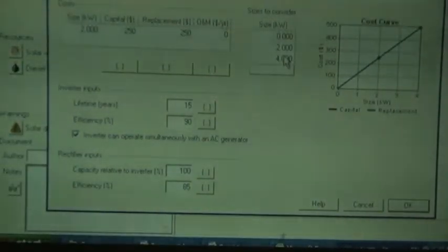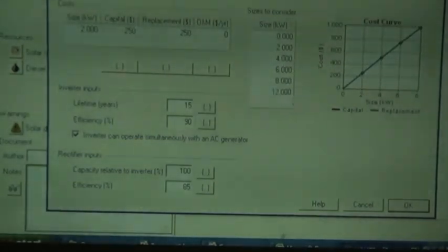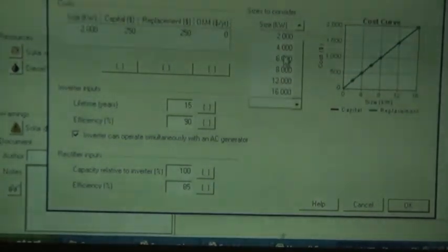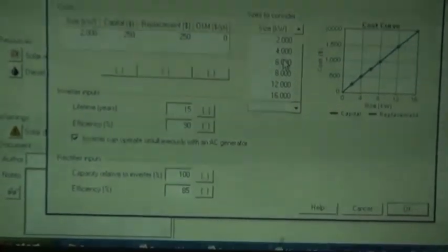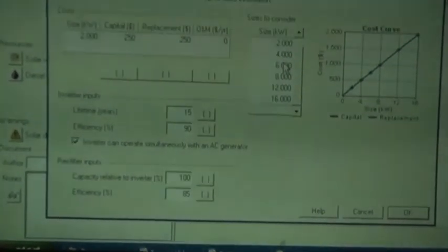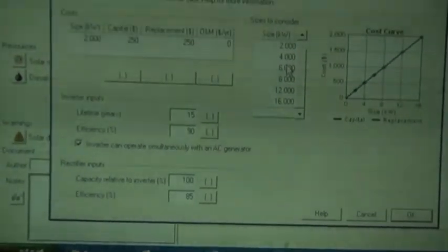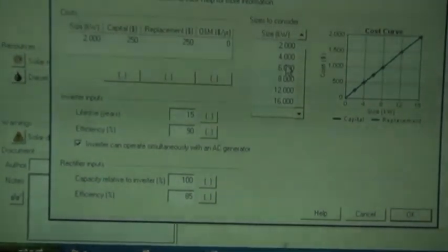Now, bear in mind that this doesn't work this way sometimes. Sometimes it depends on your genset, whether it is a 2-phase or 3-phase genset. If it's a 3-phase genset, then for the rectifier you usually have to configure it differently. Yes, the number changes, so you have to bear this technicality in mind while inputting the data here.